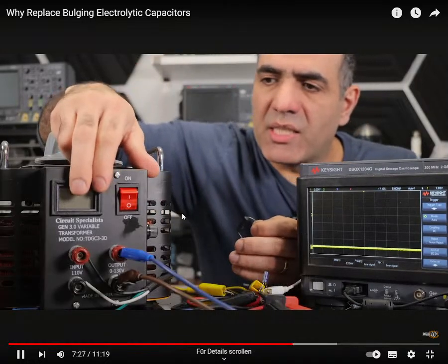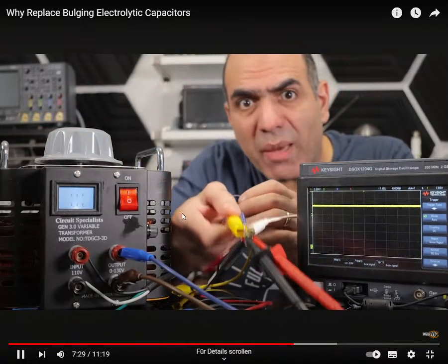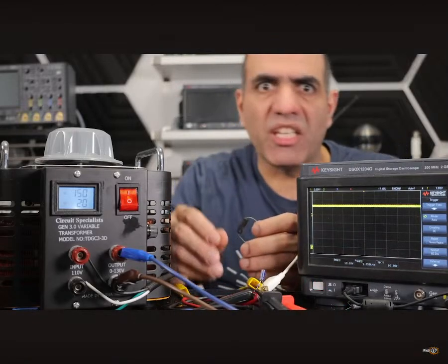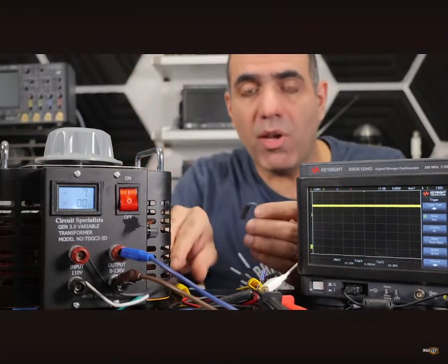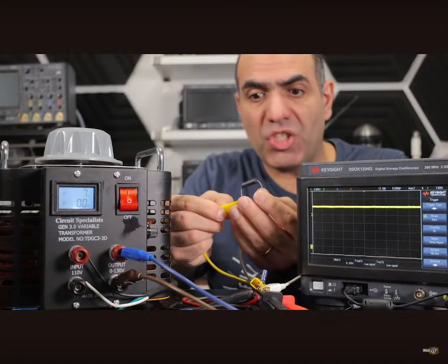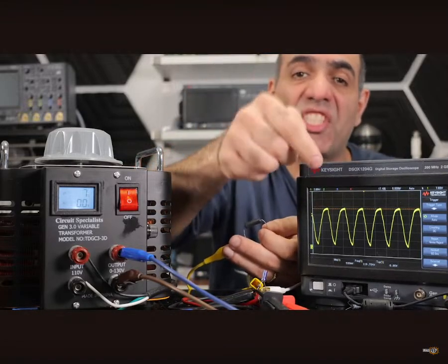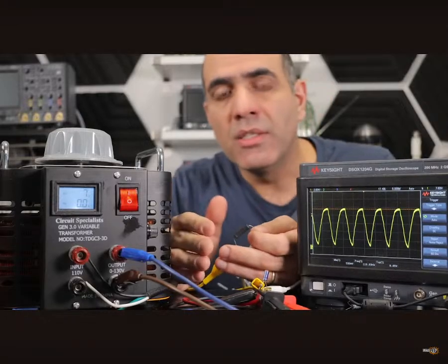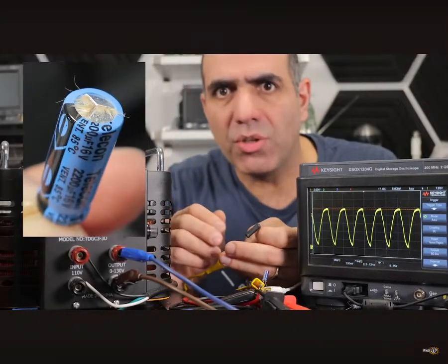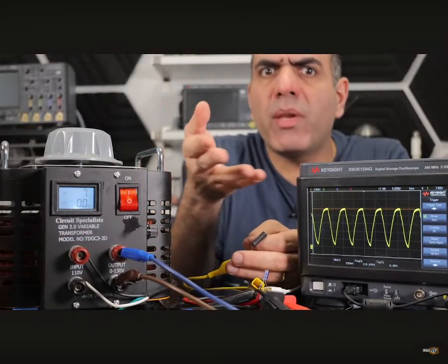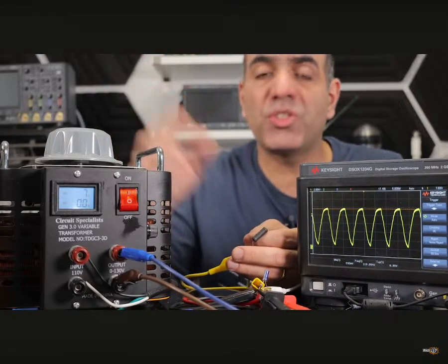But if I connect a smaller 10 microfarad capacitor to my circuit, let alone the higher ESR, with the same load, the capacitor discharges so far it can reset circuits constantly. So anytime you see a bulged capacitor, you should replace it with preferably better parameters so they won't degrade the same.